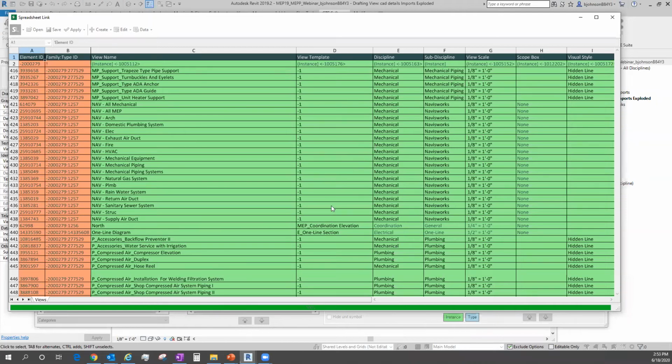If you're not involved in the projects, if you're not hands-on, before changing all the view templates to the one you think is supposed to be correct, I would check with users or the PM just to say, hey, you've got 57 objects on sheets that are not using view templates. Do you want this fixed? Or is there a reason you're not using the view template? If you're not using the view template, you could have duplicated it, made the changes, and applied those so they all do have view templates, and then I don't have to play CAD copy anymore. So things like that can make things much smoother, be better communication for all parties, and help you meet and maintain your standards a lot faster.